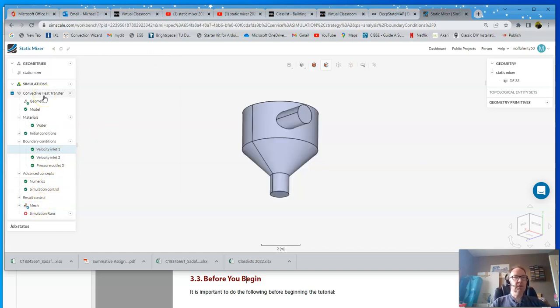And so that's the bare minimum of what we need to set for the fluid. We set the type of fluid, set the velocity and the pressure on the boundaries, and the temperatures. Then the software is going to solve for every quantity, velocity, temperature, and pressure inside the static mixer, and we'll be able to get the velocity and the temperature of the fluid coming out.